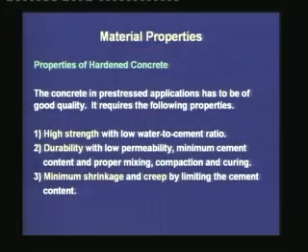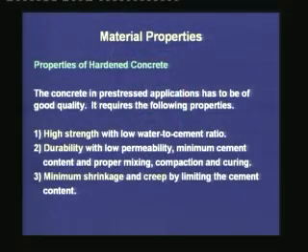The concrete in prestressed applications has to be of good quality. This is a very important statement because in prestressed concrete, the concrete is subjected to compression from the transfer of prestress. The concrete requires the following properties. First, high strength with low water to cement ratio. This is the primary requirement of concrete in prestressed structures, that it has to be of high strength.